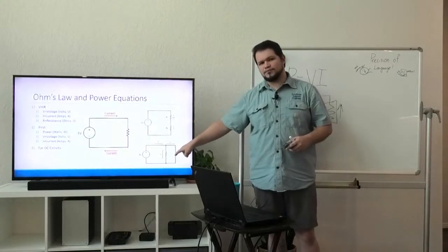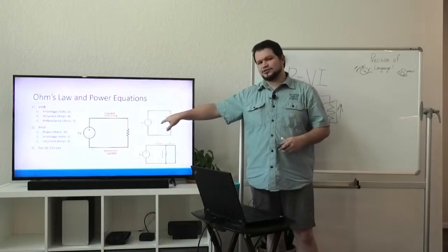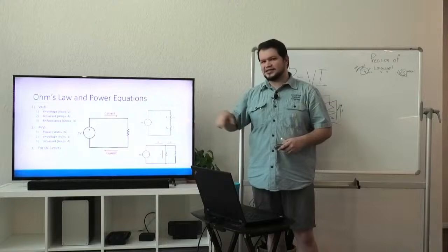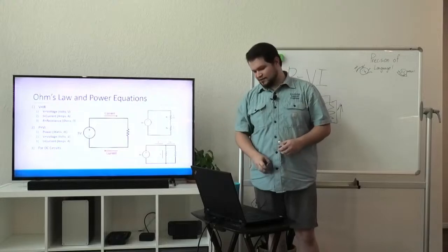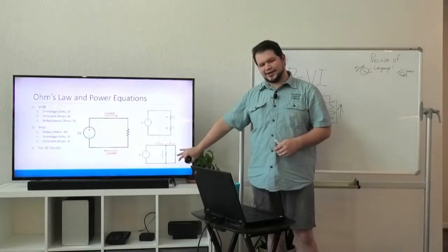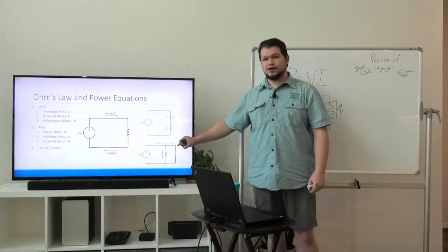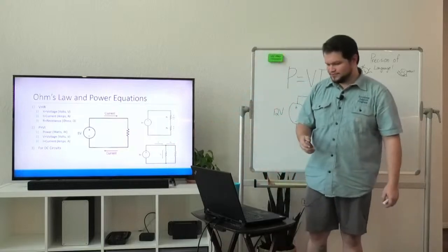In most of our components, the control hub makes everything parallel, not necessarily series. Sometimes there are things that will be put in series, and that is important to know if you're troubleshooting, but most of your items are going to have a constant voltage across all of them, and the current from your battery will be split up to all of your components.